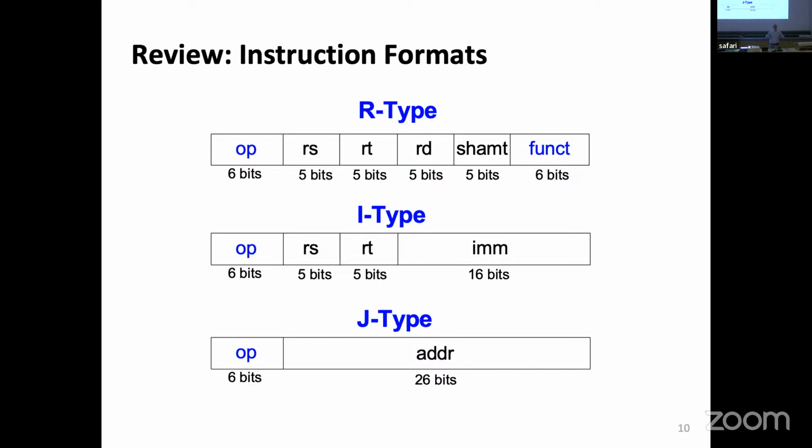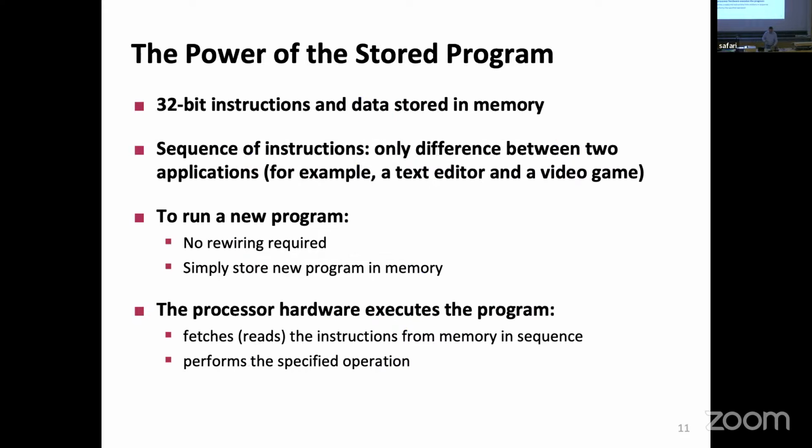Instead of making 5 different instructions, maybe some where I don't need an immediate, maybe one where I don't need a register and have 3 different versions of it, I'll just use one. And this is also the reason why this 0 comes up a lot. We have a number of operations where we don't want to use a value, but we need a useless value so that I can go through the instruction. And 0 happens to be that one in a number of cases.